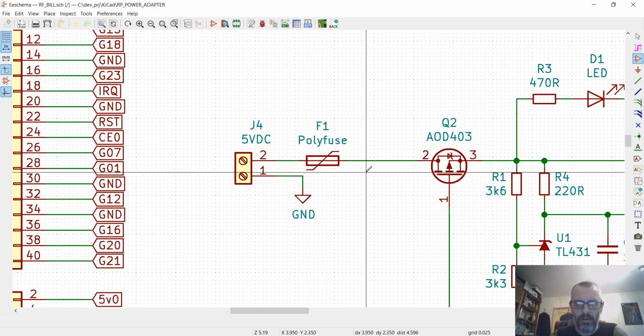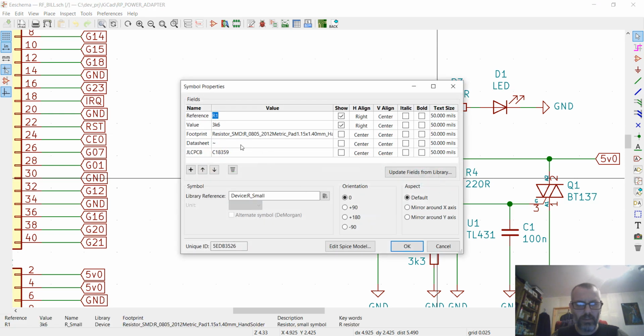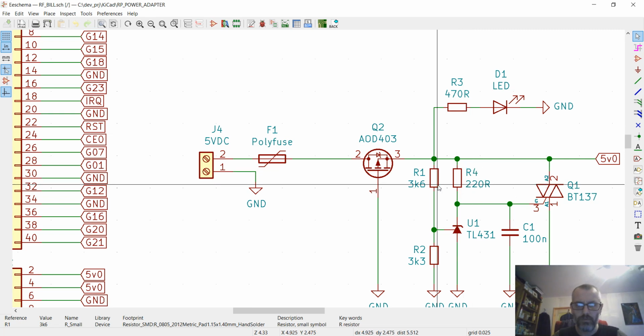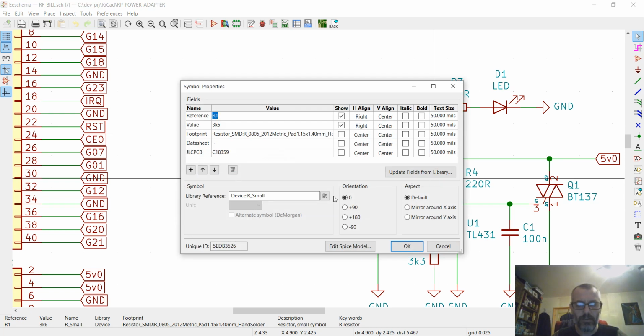I found a plugin, a utility written in Python, where by adding another field in the schematic, in the property of the part, and assigning the ID of the part that I'd like to use in that particular place, that piece of software would generate the bill of material that is compatible with JLCPCB. But I didn't find any way to have this assigned directly in a library.